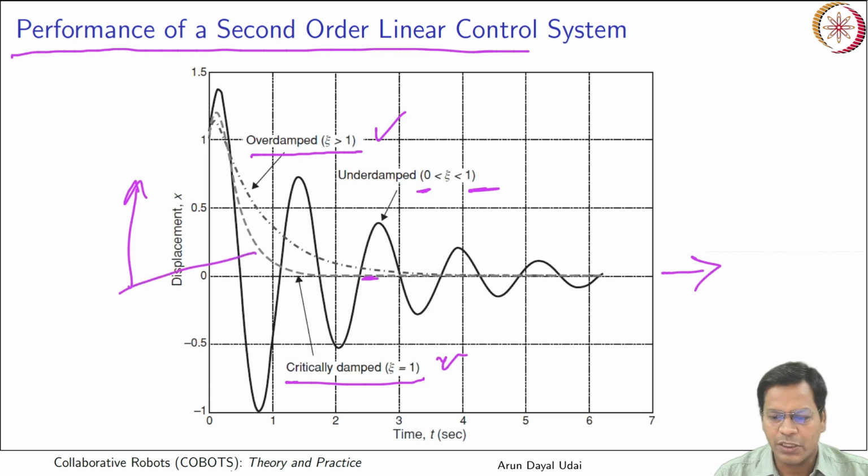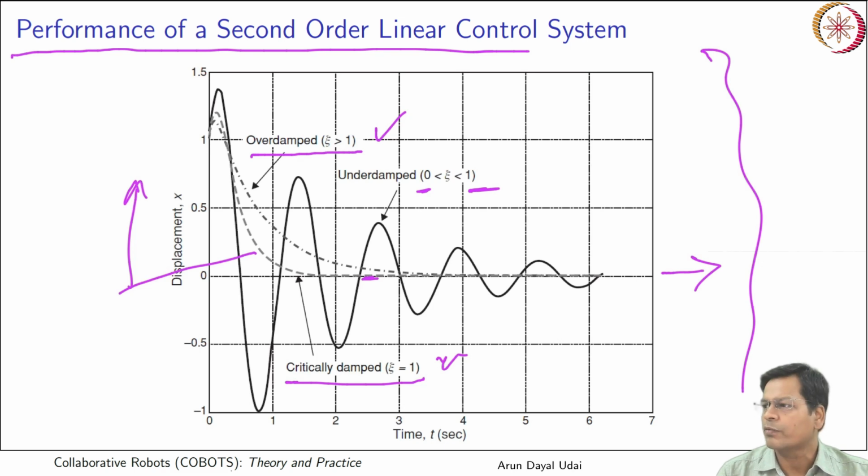So everything can be seen here. So this is the plot of the system. So you already know where your roots lie. So based on the roots and their location in the complex plane, you can decide how your system is going to behave. So you know how to get the characteristic equation of your system, and you can find out the roots. You can say how is my system.